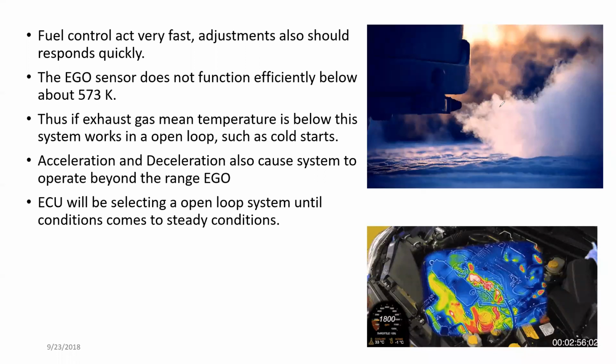To fix this, the simple system adopted by the manufacturers is to keep the engine management system as an open loop control system for some time, until the engine comes up to operating temperature.